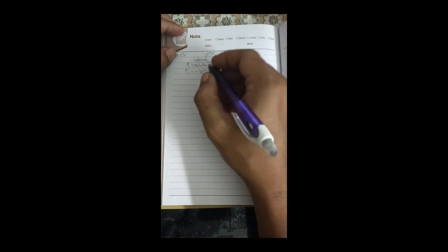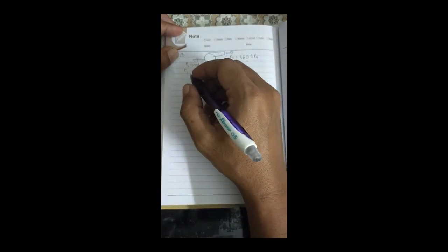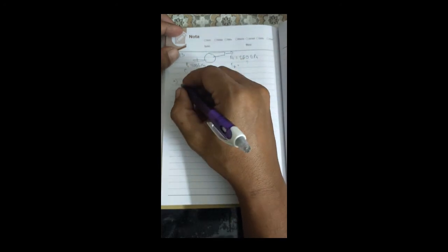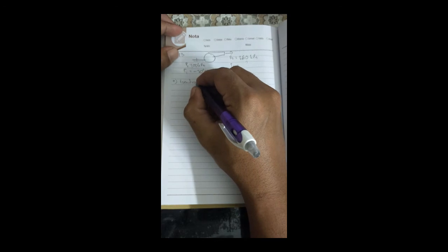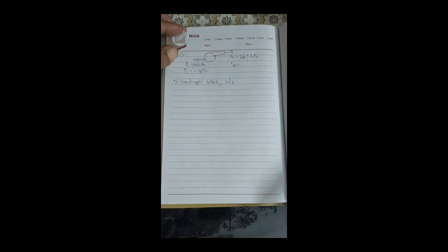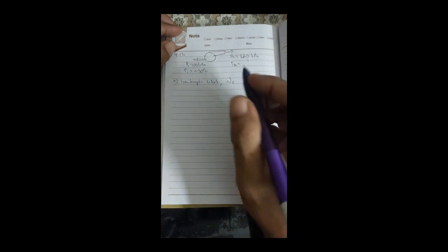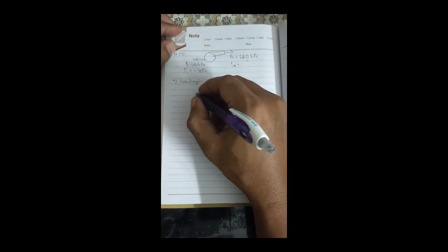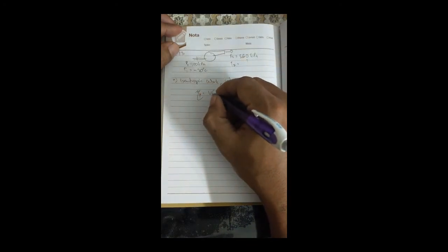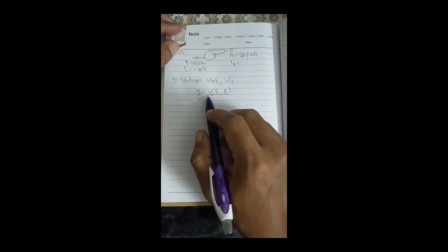We need to recheck, as the question asks for the isentropic work, so we need to know the value of ws. The isentropic work for a pump is v (P2 minus P1), as a pump operates at constant volume.